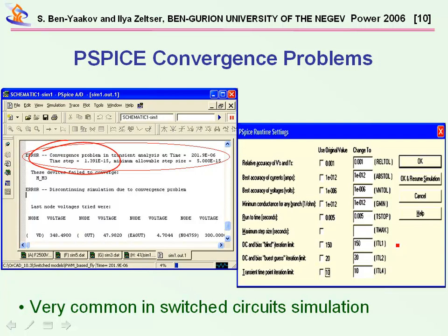That is, if you have a voltage which is changing very fast, as you have in power electronics, the problem is severe, because the simulator is actually changing the step size, going back and forth. So therefore, it will eventually hit the point that the step size is too small, and you have either to relax the resolution of the computation or the accuracy, or do some other thing.